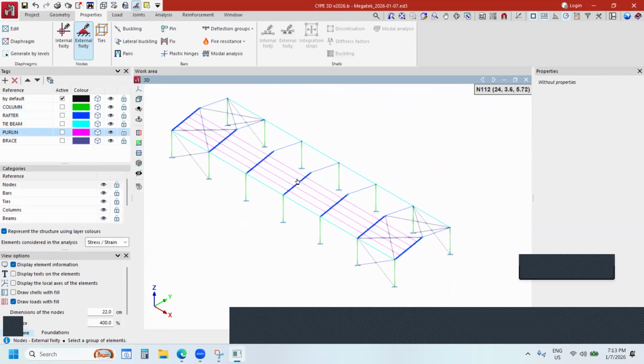Another option that we can go through is releasing the member ends. The thing that you asked me about, the simply supported, for example. It is also about the connection design. For example, you have the shear connection, or maybe the moment connection or rigid connection, or maybe the semi-rigid connection. So you can just go to the release option, and you can assign a proper stiffness if you have the semi-rigid connection. So you can assign a specific stiffness or rotational stiffness to the end of any member.